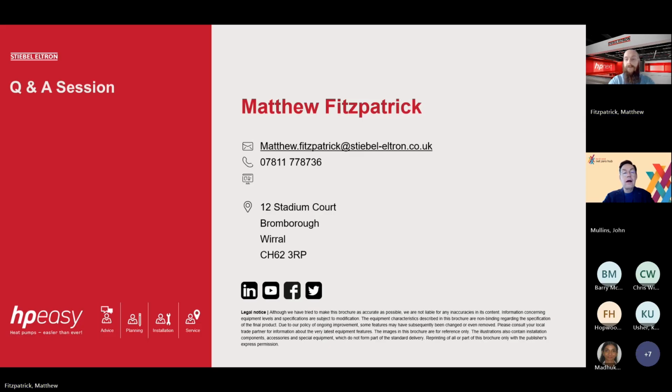And Matt, in terms of what's actually happening inside the heat pump, we've got a compressor and an expander valve. And if you stand next to a heat pump in winter, they're blowing out cold air as they extract heat from the air. In summer, if we're on cooling, then clearly my understanding would be it's running in reverse, and that heat pump unit will be blowing out hot air exactly as an air conditioning unit goes. But if we want to oscillate between heating and cooling, we've got this large water buffer tank sitting there that we would then need to heat or cool before we can actually start providing a temperature change to the radiators or the underfloor heating. Yes.